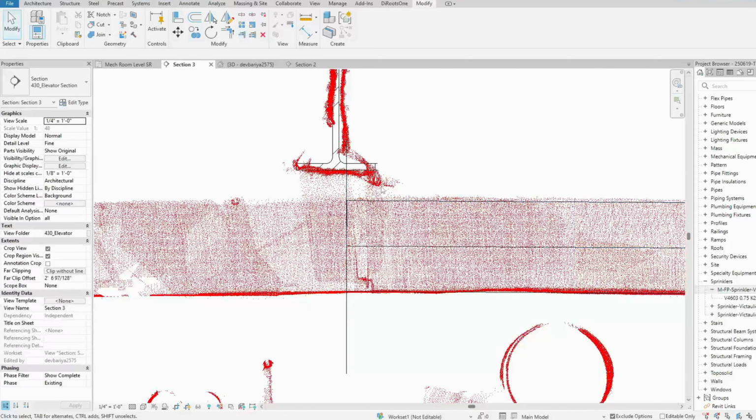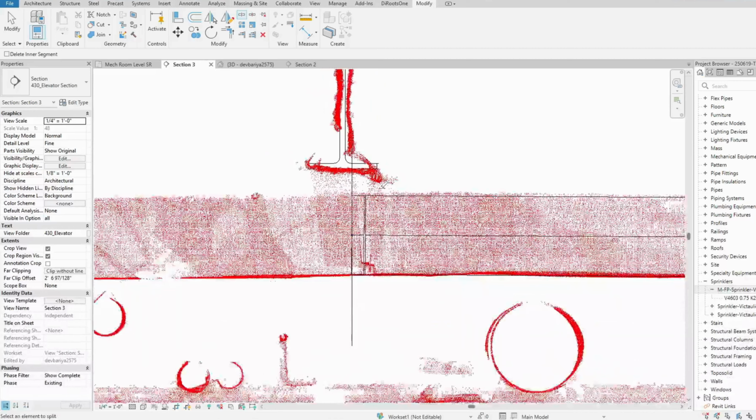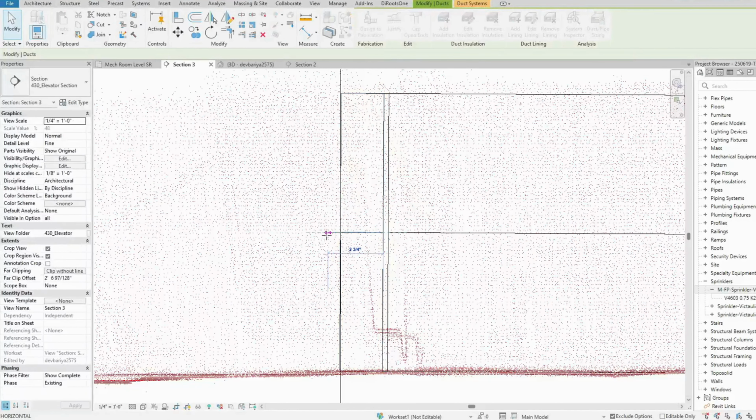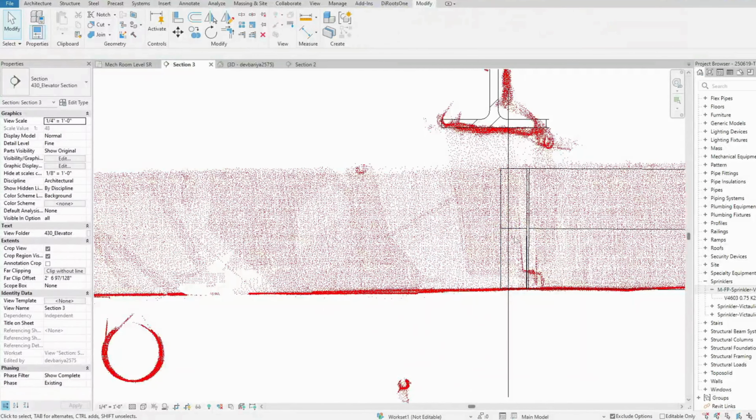Switch to the 3D view now and select your ducts. In 3D, you can better understand how your system is placed in space, see how fittings automatically adjust, and use the Align or Move tools to refine your layout. Use the System Inspector tool under Analyze tab to visually trace your duct network and confirm connections.